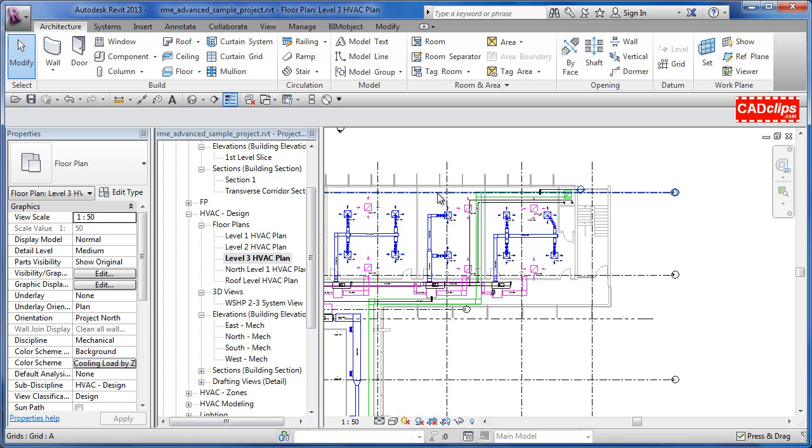So the columns and the beams and the edge of the floor slabs, and you can tie stuff and offset it from the grid line. It doesn't have to be on the grid line. It can be constrained to the outside so that it's 300 millimeters or a foot past it or something like that. So you can definitely constrain and tie your elements and object and sketch lines, which we'll talk about.